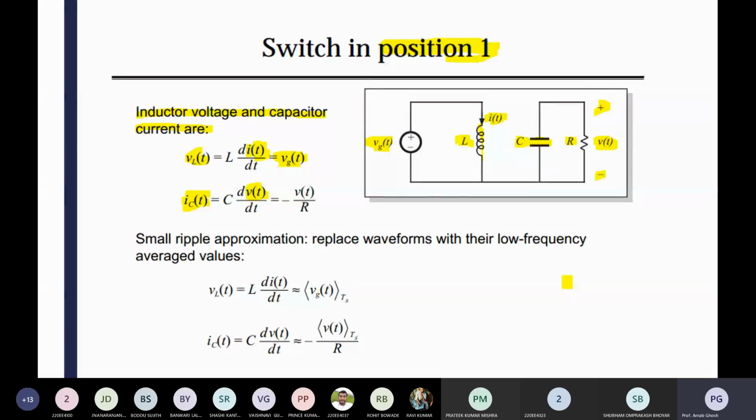Based on their dynamic nature we have to design the controller. Arbitrarily we are not going to design any controller, so definitely there should be some motivation. Why are we selecting classical controllers? Classical means you can select a P controller, PI controller, lead controller, lag controller, lead-lag controller, lag-lead controller. Then we also use some K factor based controllers, meaning PI plus lead controller. What is the motivation? Why are we discussing such kinds of classical controllers?